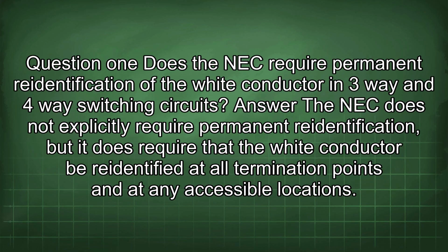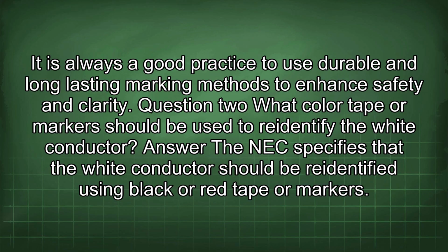Does the NEC require permanent re-identification of the white conductor in 3-way and 4-way switching circuits? Answer. The NEC does not explicitly require permanent re-identification, but it does require the white conductor to be re-identified at all termination points and at any accessible locations. It is always a good practice to use durable and long-lasting marking methods to enhance safety and clarity.